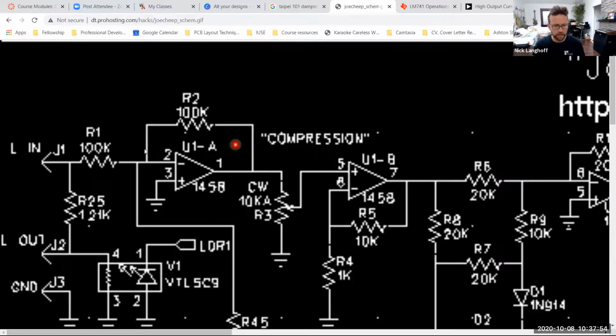So in this case, it seems like the designer wanted to isolate or buffer the signal coming from the outside world. You don't know what happens in the outside world. You design a product and some user connects whatever cables to it and runs them wherever they do. That cable could be wired up in a coil stuck next to a highly inductive load like a motor on an AC unit cooling a house. That's not the best idea. Or maybe you're near a radio tower.